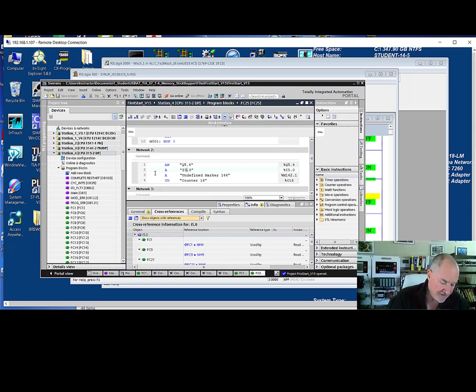So maintenance people have to fight through this stuff. So network 2 was counter 16, and I found that I5.0. And then I might, in my plant, have something that I need to write down saying I5.0, which was such and such a sensor, was bad. So I have to go get a new one and wire it back into the system, test the system, start it back up, and I'm good to go.